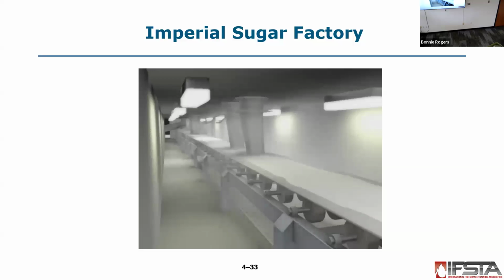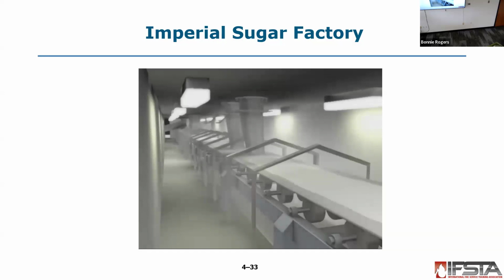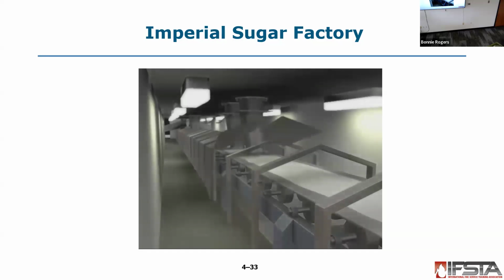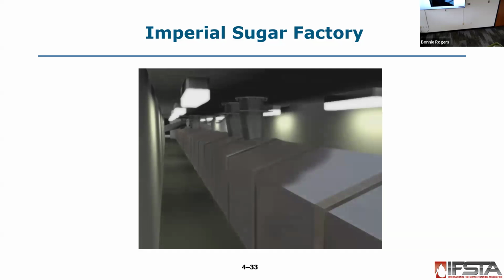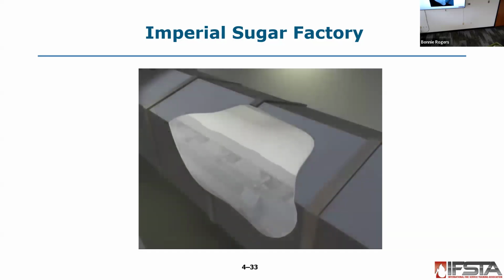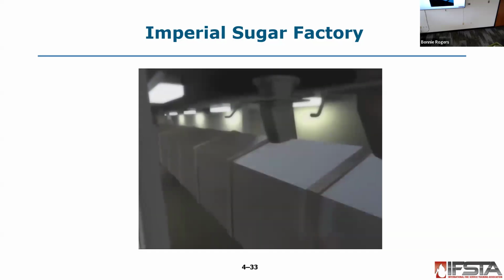However, in 2007, the company enclosed the conveyor belt with stainless steel panels to protect the sugar from possible contamination. The enclosure was not equipped with a dust collection system. As a consequence, sugar dust would now be trapped inside this enclosure.